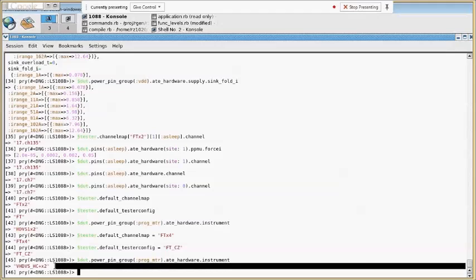So that's the concept, because for the digital network, it's very common for us to have one test program with multiple channel mappings in it. So when we validate, we can just load a probe channel map or the final test channel map and then validate on that specific tester. By being able to have multiple channel maps and tester configs loaded, we can generate one giant program for everything.